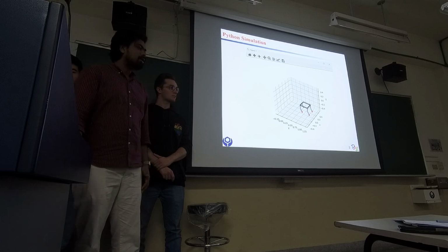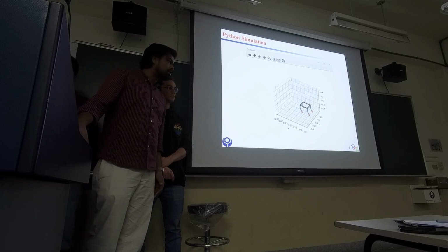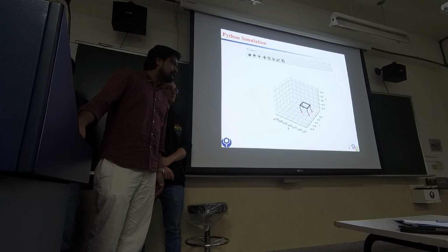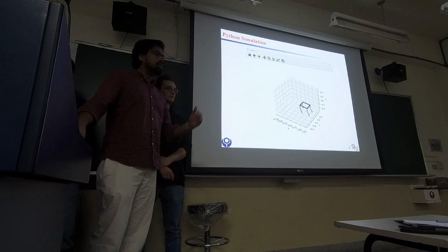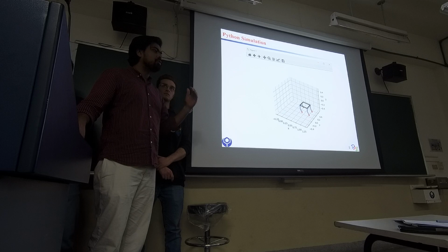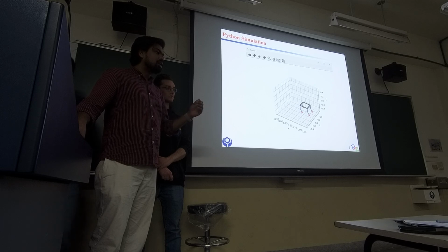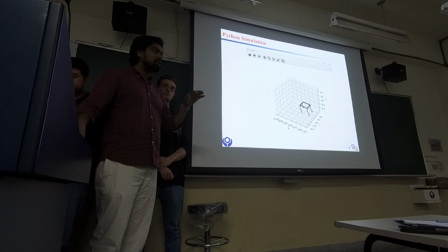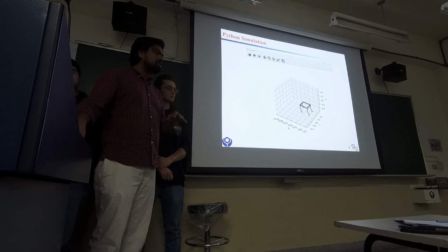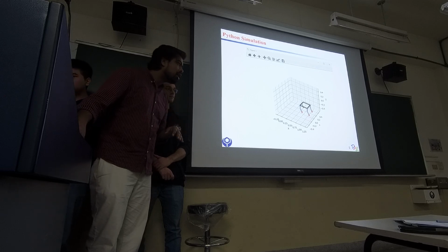Yeah, so the boundary condition, how do you set up your Adams simulation? There is an option inside, so we have to set the step and the time when the step has to move. According to that we give the initial angle and the last angle, and it manages the rest. And the force? Yeah.